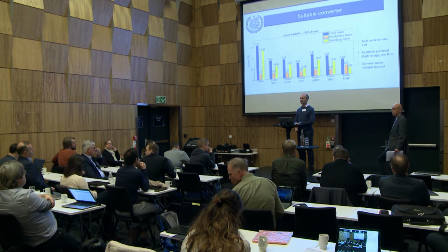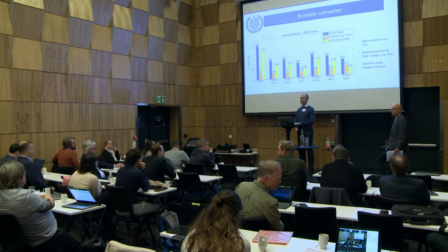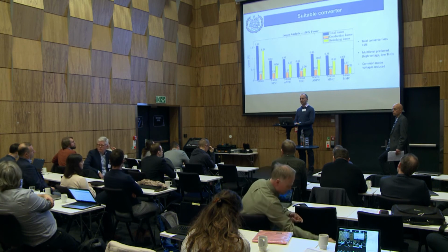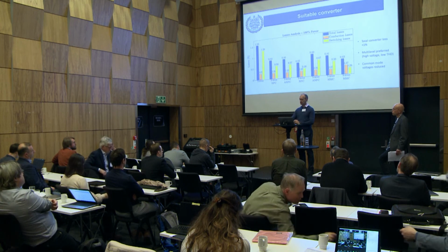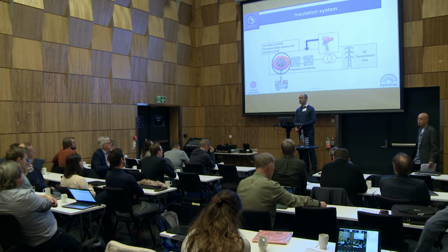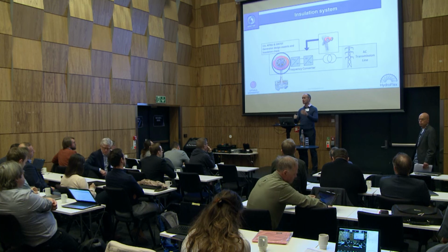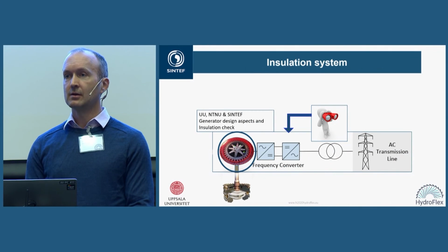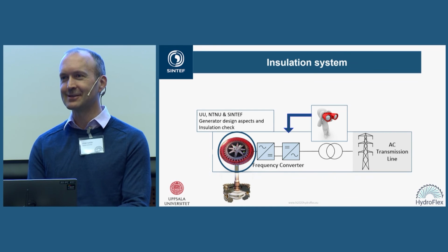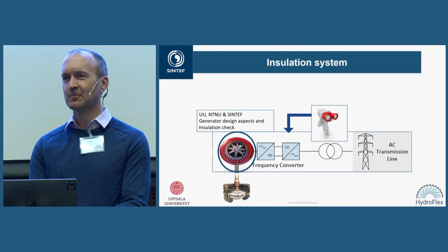At the best efficiency point, when the turbine operates, perhaps these power electronics needs to be bypassed. That's definitely an option. Maybe I didn't show it here, but you could actually bypass the frequency converter altogether if you want to operate it continuously for a very long time. Absolutely. But then the best efficiency point has to be at synchronous speed of the generator. Yes, so that's not a problem at all, right? No, to bypass is a breaker that you have to install, and it is known technology. Thank you.